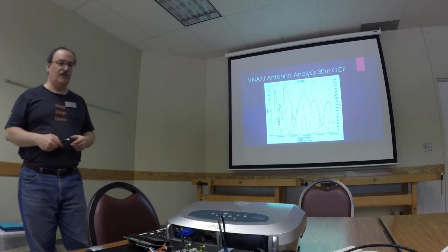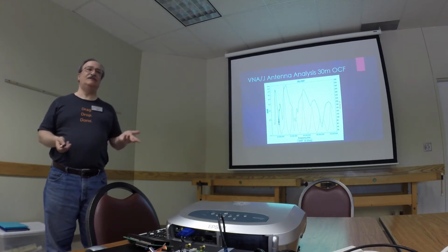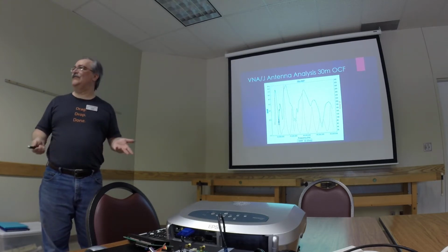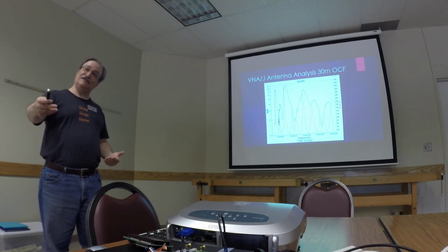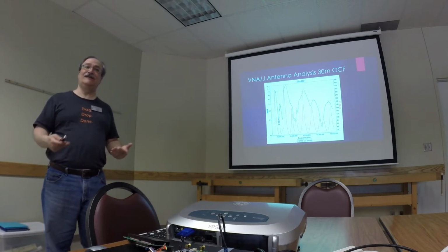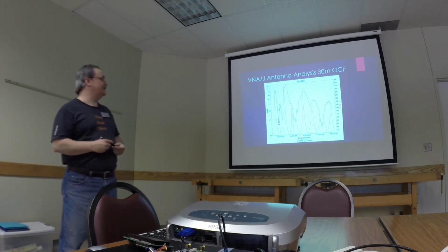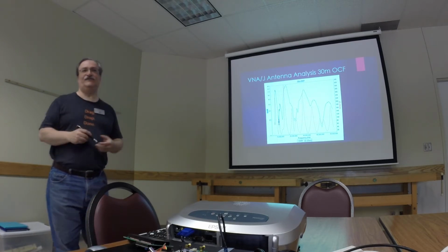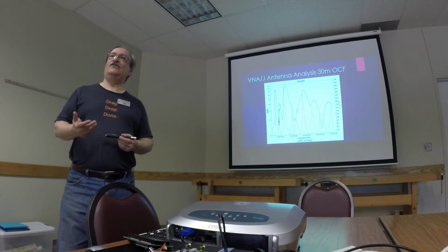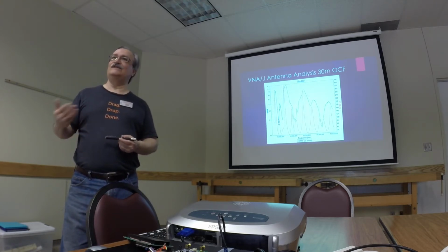And at 1.8, 1.9 to 1, I'm already using 0.2 of a watt. I don't really want to lose anything more at 0.2 of a watt, because it's going to be logged as 0.2 of a watt, even though it effectively is less than that. I should get the best out of it that I can get. Well, it turned out that the whole reason for this is because I was seeing 25 ohms at the coax on the transmitter. Times 4 is 100.